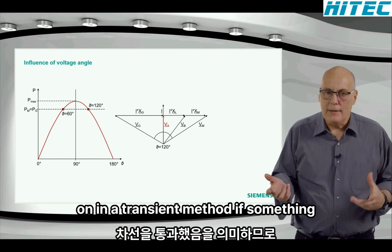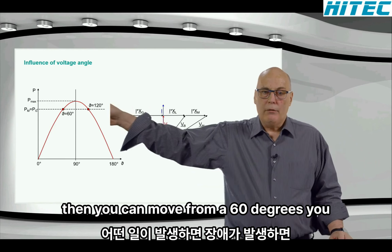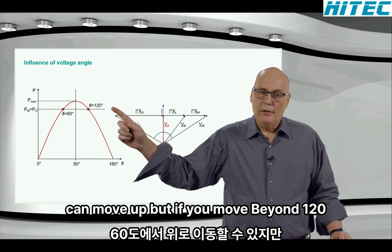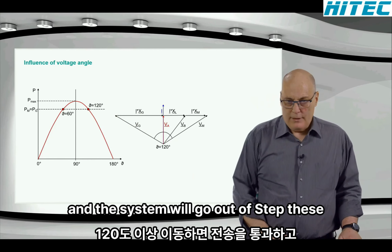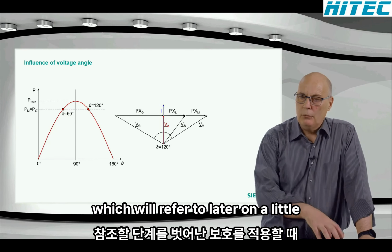So in a transient method, if something happens, there's a disruption, a fault, then you can move from the 60 degrees, you can move up. But if you move beyond 120 degrees, you've passed the transient stability limit and the system will go out of step.